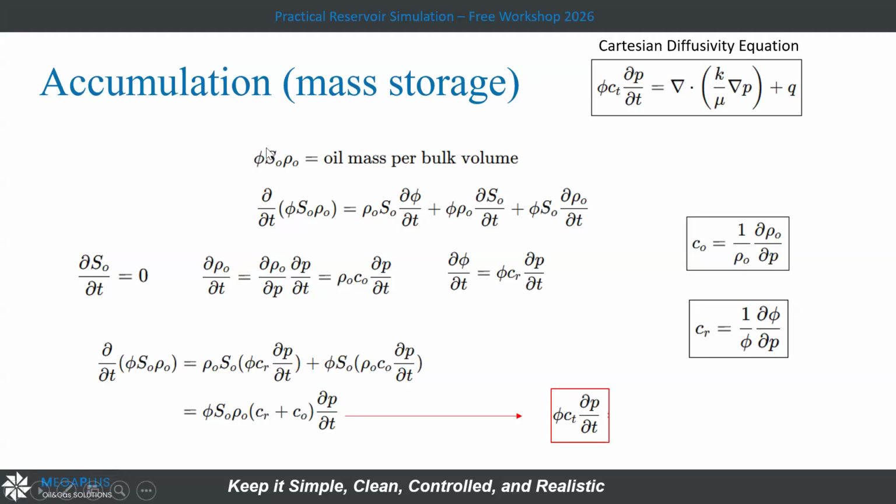this expression with time, we will split it. So you will have here the saturation change with time equal to zero. We assume it is zero, and we will multiply both in this terminology with the change in pressure, because I need to relate the accumulation to pressure.